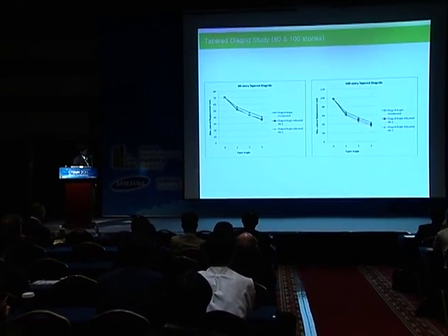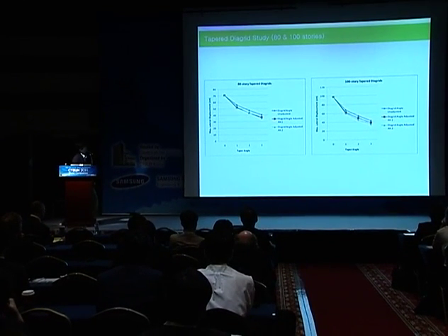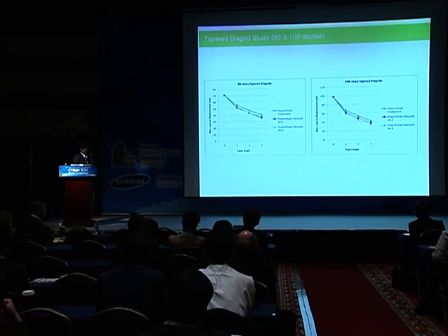Here are some more studies with the 80 stories and the 100 stories. The effect of adjusting the angles, that means again a steeper angle at the bottom and a shallow angle at the top, you can clearly see in these much taller, 100-story buildings. Now the red line and green line are separated, and the more structurally following angle configuration becomes stiffer.